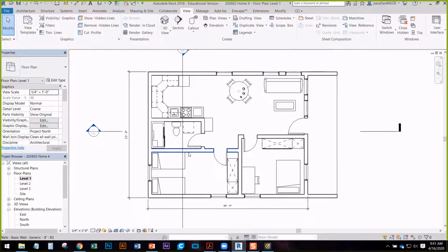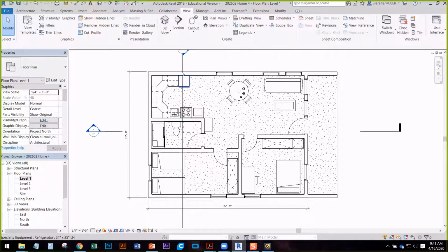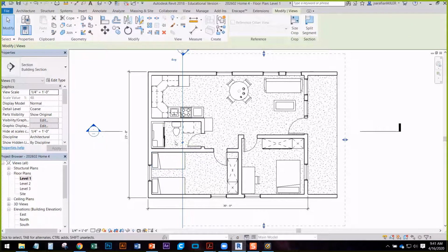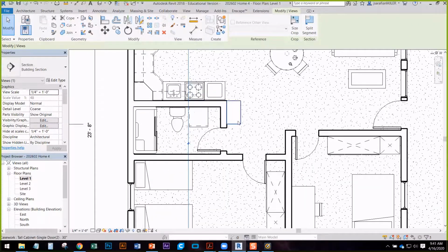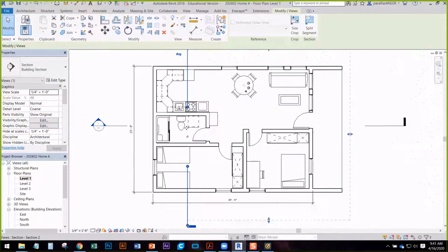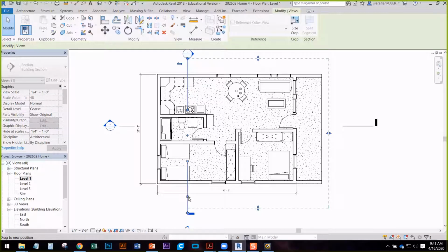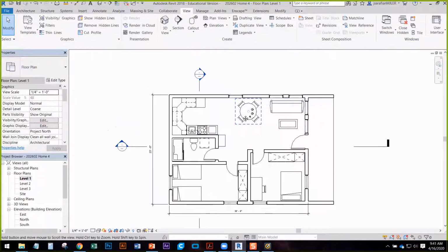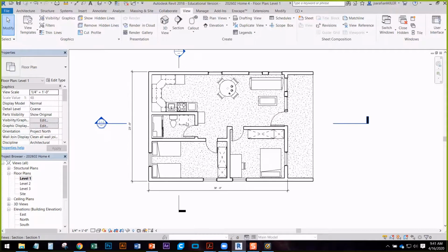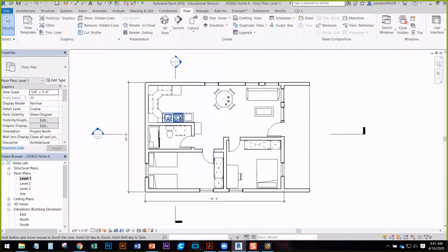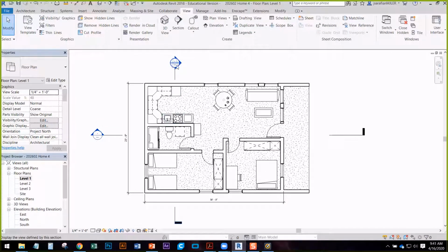The other thing you can adjust just in your plan view, I don't like to have this line cutting through the drawing. It just adds one more line that we have to look at. So clicking on this lightning bolt in the middle will break it up, and then you can pull this off of your drawing, not moving the section at all, but keeping the drawing more clean so that these are off of the page.